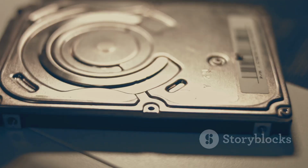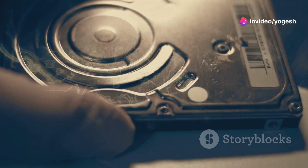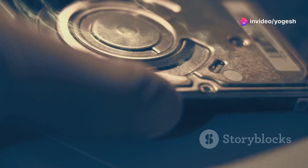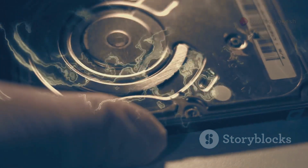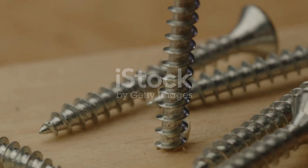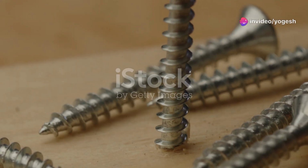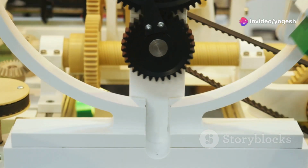A more common approach is the schematic representation, where the major and minor diameters of the thread are represented by concentric circles. This method strikes a balance between detail and efficiency. Finally, the simplest representation shows only the major diameter of the thread. This method is often used for simplified diagrams or when space is limited.